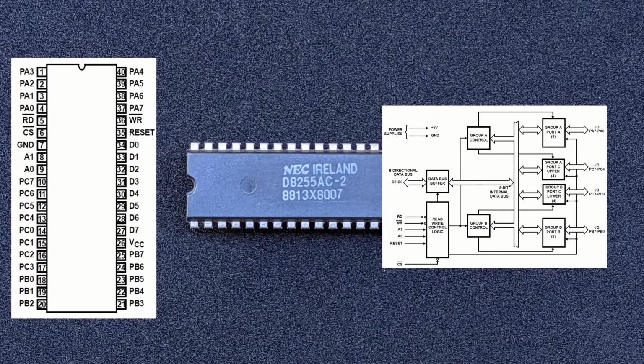Usually, at this moment, other authors would probably connect this 8255 chip, which is the Programmable Peripheral Interface. This IC is an I/O device providing 3 8-bit ports, 24 bits altogether, each of which may be programmed to be an input or output. We may decide on attaching it to our computer in the future, but today I'm gonna attempt to hook our LCD to the CPU directly.